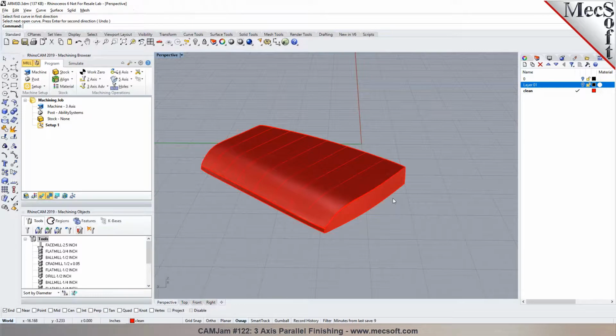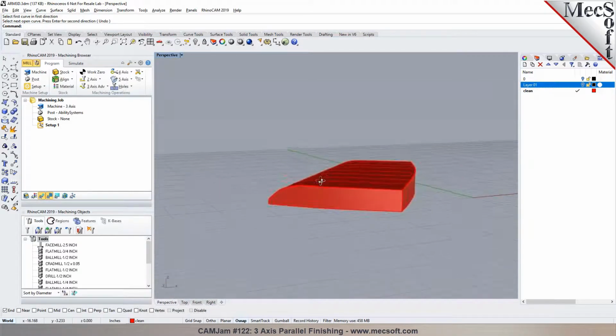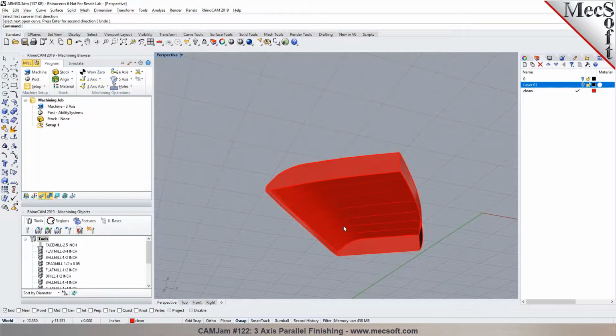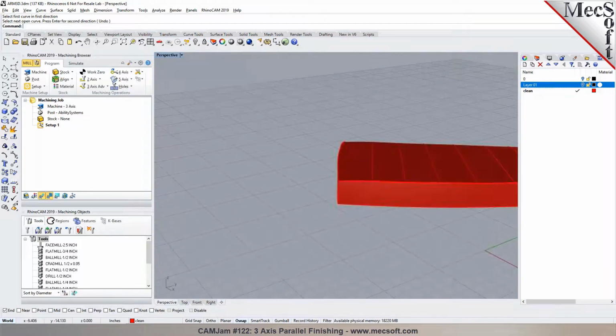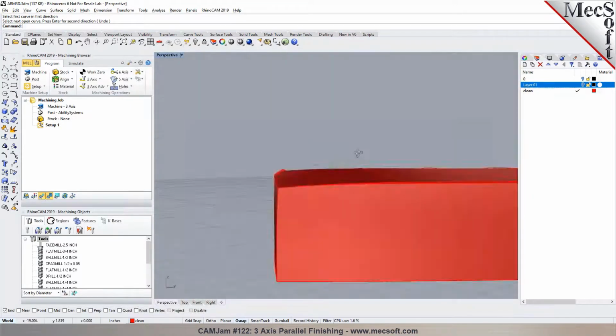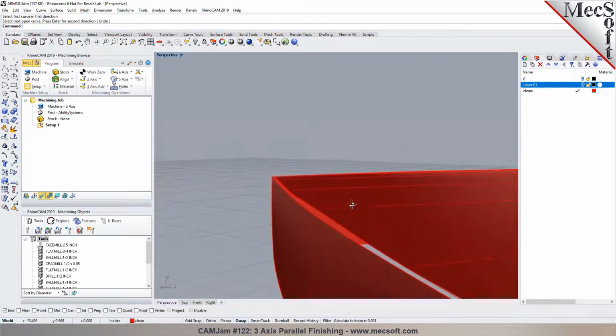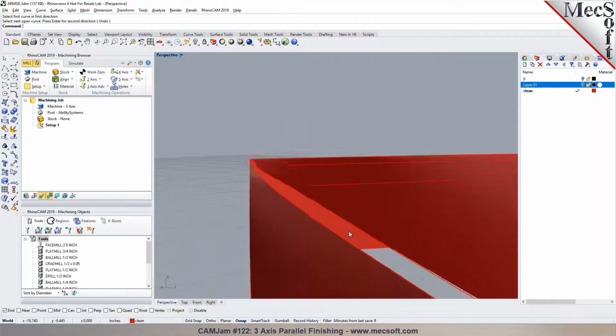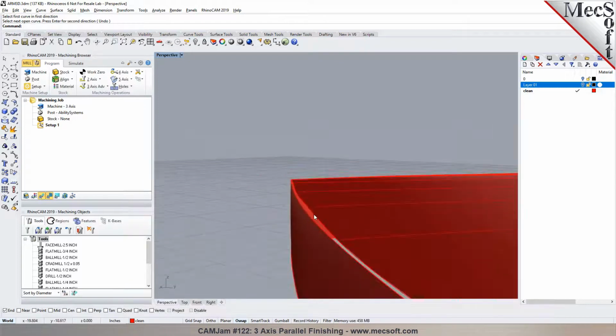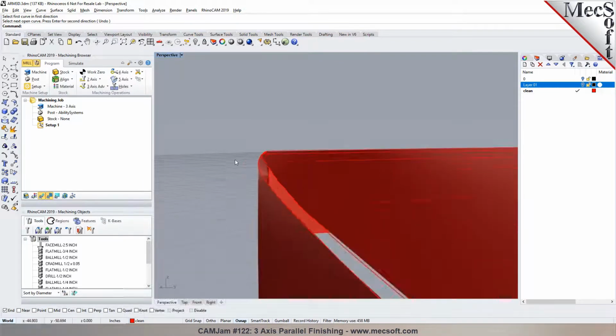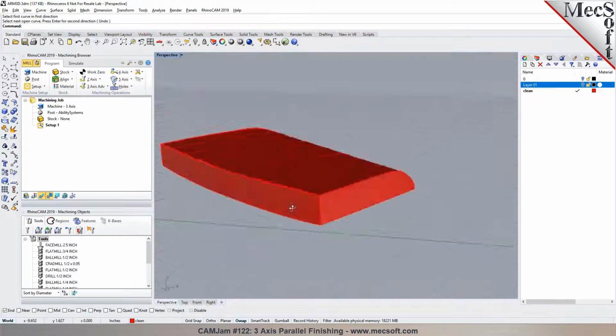Okay, so you got this part designed in Rhino, and you don't have to worry about capping the bottom because the tool is not going to cut through it, since there are no gaps or holes. And the gap you have is fairly insignificant, because it is not too big for the tool to dive in there, right?